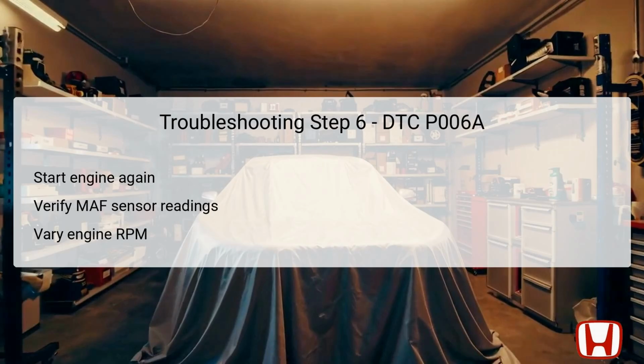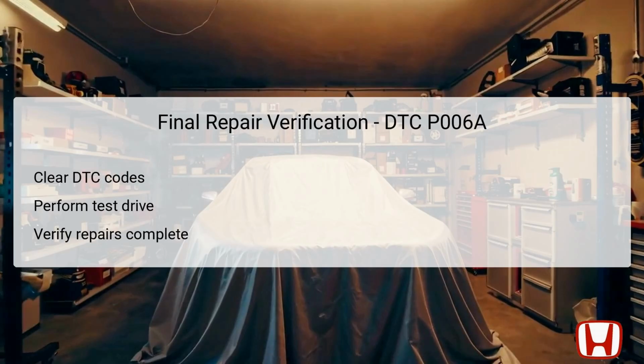If readings do not reflect expected changes, this signals that either the MAF sensor or the IAT sensor could still be faulty. Addressing these issues promptly ensures the vehicle performs efficiently and effectively, maintaining optimal fuel economy and emission standards. If abnormalities are detected in this final check, repair or replacement of the sensor might be necessary to resolve the DTC P006A.